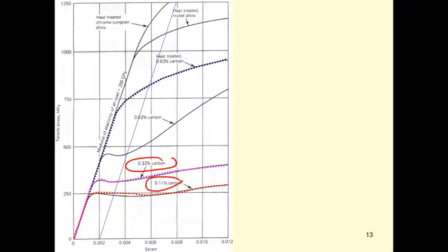And also the heat treatment also increases it. So the steel property not only depends on the percent carbon, it also depends on the manufacturing process. How? Because when you treat the steel with heat, you heat it up again, and then you control the cooling step by step. So the grain of the steel is going to get smaller and very smooth, close to the theory. That's why heat treatment improves the strength of the steel.